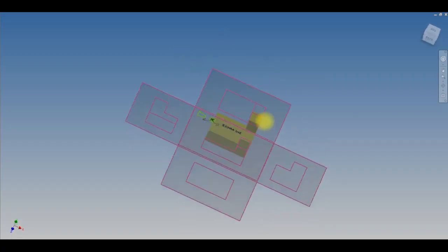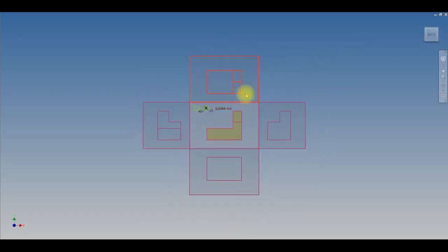The top view is looking at it from above, and you'll see that it's directly above. This isn't over here somewhere, it is directly above. This is directly to the side. If we drew a straight line across, these would be in exactly the same place. Same as this. It's incredibly important that everything is completely in line. That's what orthographic means. Remember in the first tutorial for AutoCAD, I talked about the ortho setting for drawing lines in AutoCAD. It will only allow you to draw vertically and horizontally. This is orthographic projection. It's completely in line horizontally and completely in line vertically.